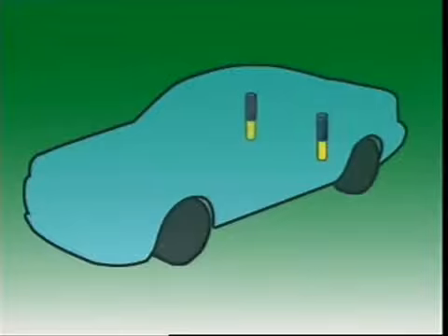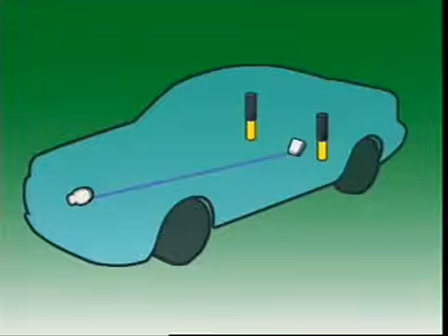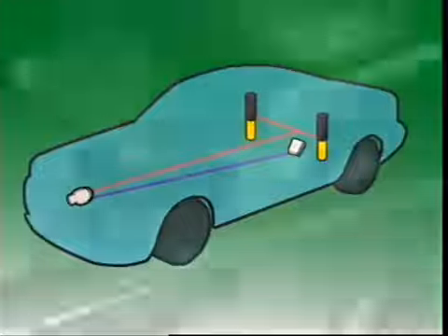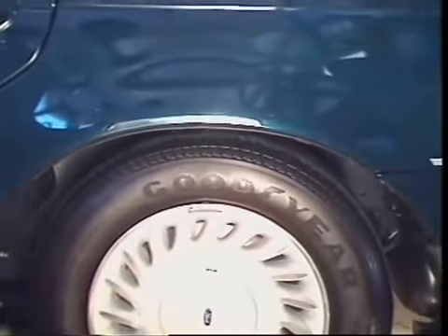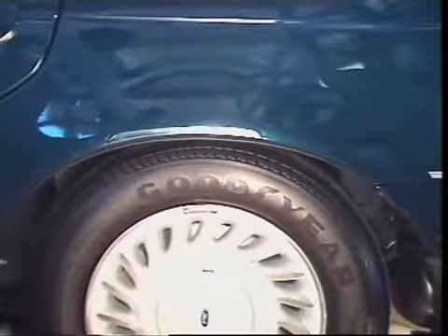It consists of air-adjustable shock absorbers fitted to the rear suspension, an electrically driven compressor and air dryer assembly, and an electronic control unit, and associated wiring and tubing. The ECU is mounted to the cross member over the rear axle, and a movable link connects it to a rear suspension member. As the vehicle is loaded, the normal suspension springs are compressed, which lowers the height of the vehicle.